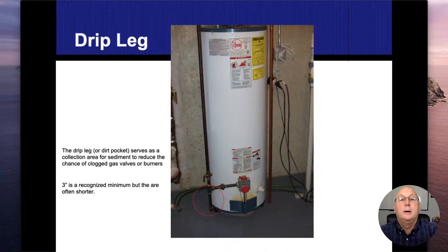This water heater, I don't know if you could see it down there at the bottom, right above the cursor here. There's actually scorching coming out of there. So that's a pretty good indicator that either we're depressurized in the area or we have a very bad gas-air mixture and the fuel is spilling out of the opening and igniting and causing that scorching to be there. But we'll talk about scorching in a little bit.